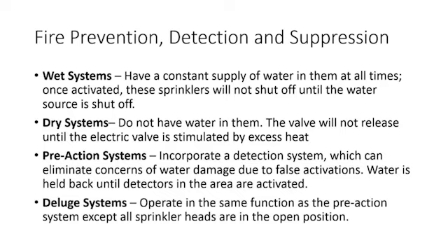You may have a dry system. Now, these don't have water in them at the go, right? So the valve will not release until the electric valve is stimulated by excess heat. So there's going to be somewhat of a delay, right? We have a pre-action system. Now, this one incorporates a detection system, which could be part of that security system. Now, this can eliminate concerns of water damage due to false activations.